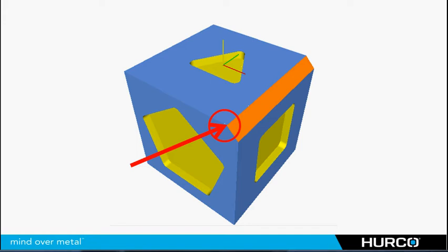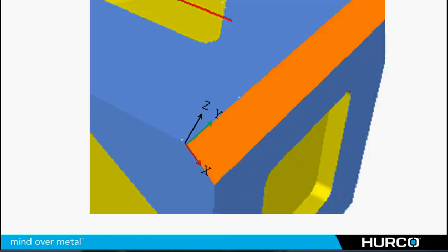So when I put my x-axis origin point in, I'm not going to go the full 3 inches all the way over to the side. I'm only going to go 2.5 inches. Then I'm going to move my 3 inches negative towards the front of the block, and I'm not going to move 0 at all because I'm already on the same surface that I want to machine my feature. So my new origin point is going to be where that red arrow is pointing. It's going to be a positive 2.5 inches in X, a negative 3 inches in Y, and a 0 in Z.